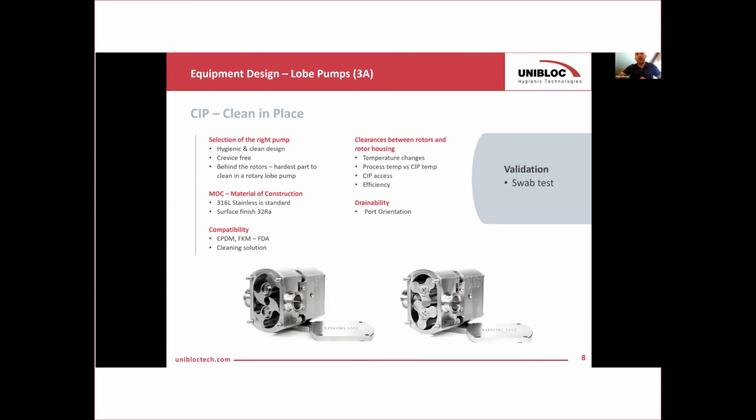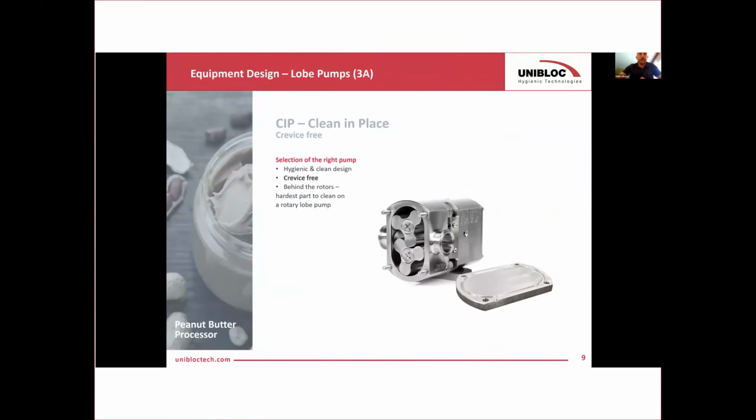And that can be done with a swab test that we're probably familiar with now, a swab test from the COVID era. But that is also in the process plant, that you swab the equipment and you test it with an ATP type of method that is producing a glowing light and identify potential bacteria left in the pump. There, I cannot stress enough to then seek out equipment and pumps that are crevice-free when you do CIP.